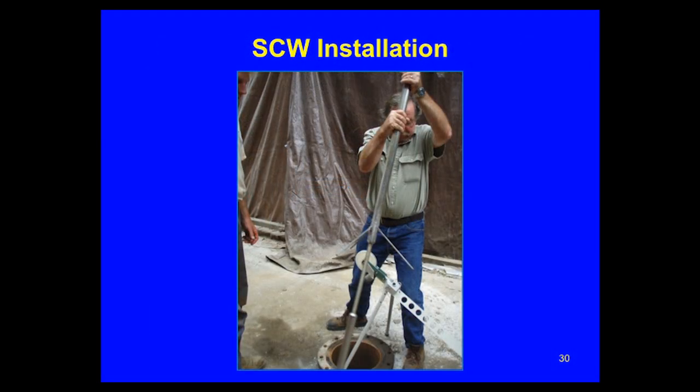So I talked about drift analysis. The state of New York gives us a permit to drill this deep well, anything over 500 feet. But when they give you that permit, one of the conditions is you have to monitor where that borehole ends up. And when you drill a hole, it's not a given that you're going to get a perfectly plumb straight hole. The borehole does wander based on differences in the strength of the rock and how that bit advances. So it's not unusual for a 1,500-foot hole to start at one location and wander 50 feet.